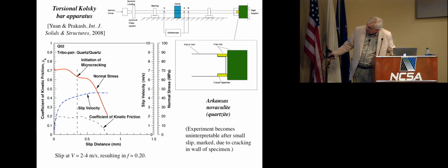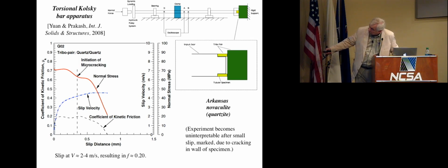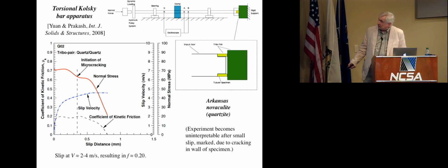But what you find is that the actual coefficient of friction falls down to around 0.02. So a massive drop from normal friction due to the fact that there's high sliding velocity. And how high is the velocity where you read this on the right scale? So it's of the order of a few meters a second. Now, experiments have their problems. That's why I'm a theorist.